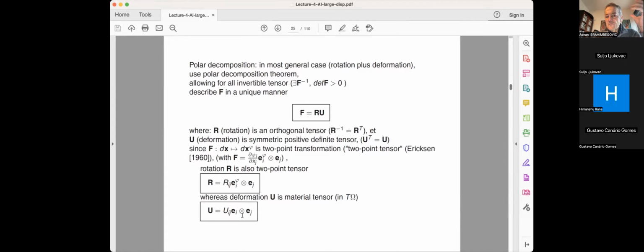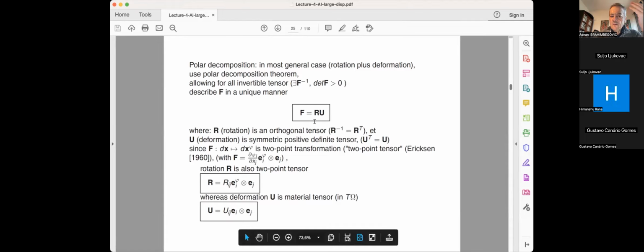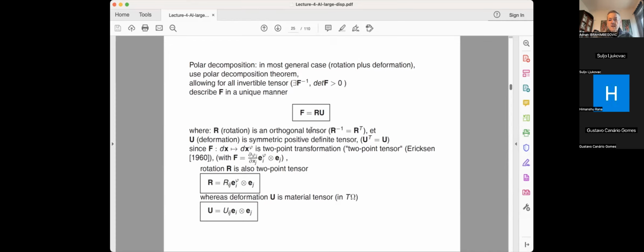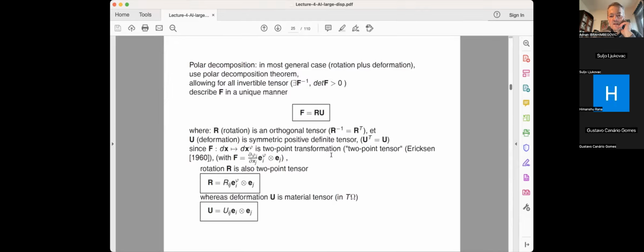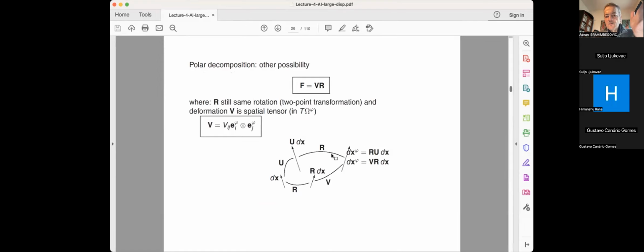So next to the deformation gradient, I have now the stretch tensor, in particular the right stretch tensor, which gives me the measure of deformation directly without having to talk about rotations, unless, of course, I have to compute the polar decomposition to find U as opposed to R. Now, this is one possibility, and this was sort of a material strain measure.